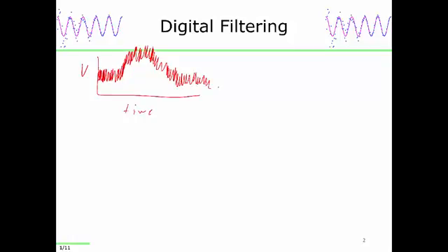And the question is this. Is it better to sample at the maximum bandwidth of your electronics, which is illustrated here, or to sample at the bandwidth of your signal, which is not necessarily matched to the bandwidth of the electronics? Now, if you were to sample with respect to the bandwidth of the signal, you can see the signal has sort of a rolling feature underlying it, then you might sample less frequently.